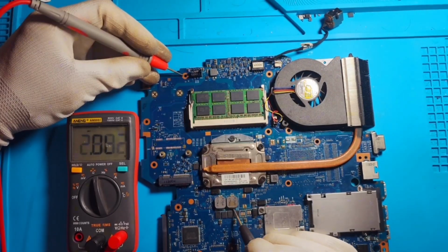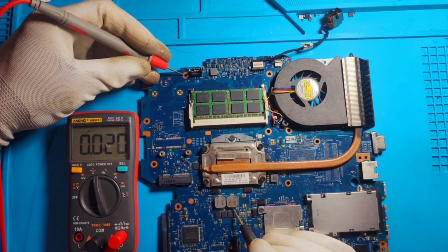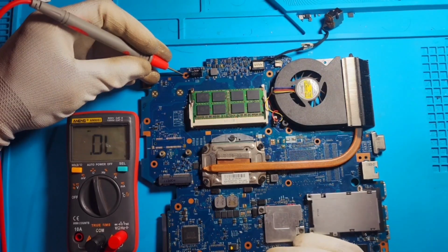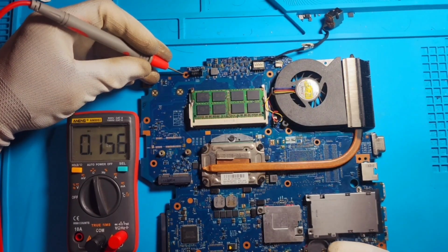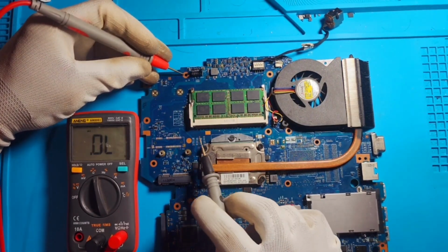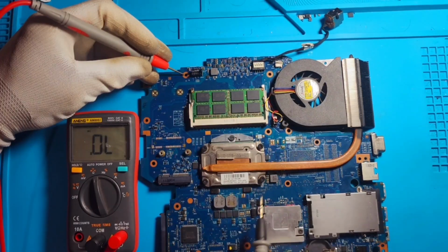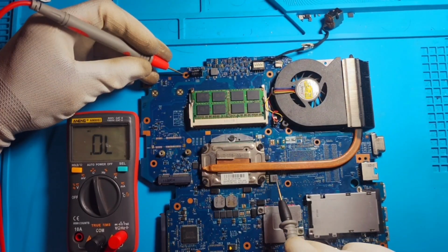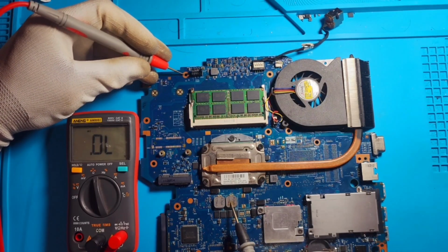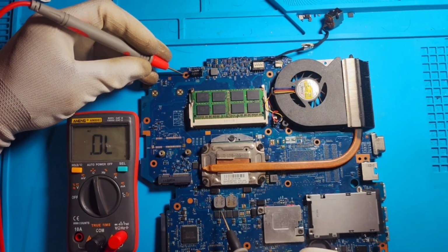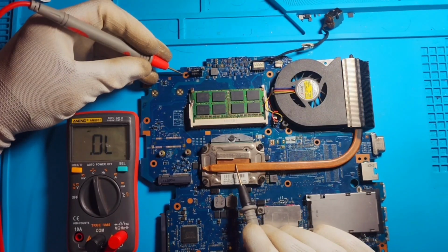So you can see on the multimeter it's 0.021, and this is 0.064, and this is 1.56, sorry, it's 0.156. Okay, so when you look at the core sections, the supply for the CPUs, the coils beside the CPU will have a low resistance when you check the diode value for the lower MOSFETs, so that is normal.